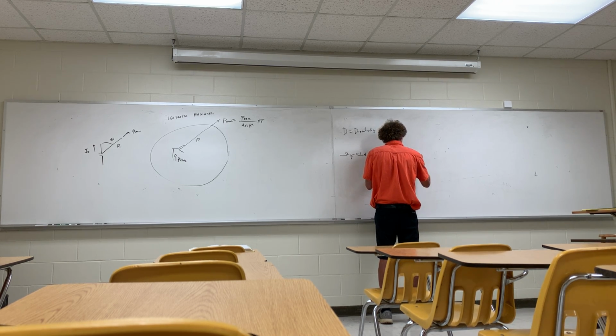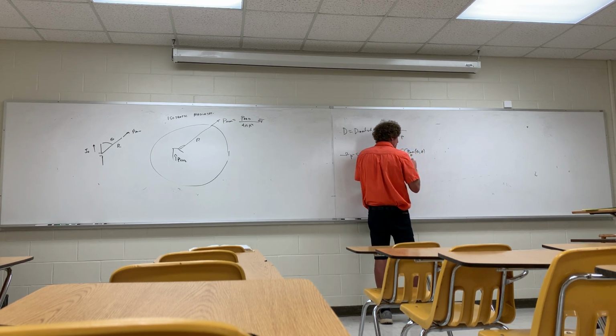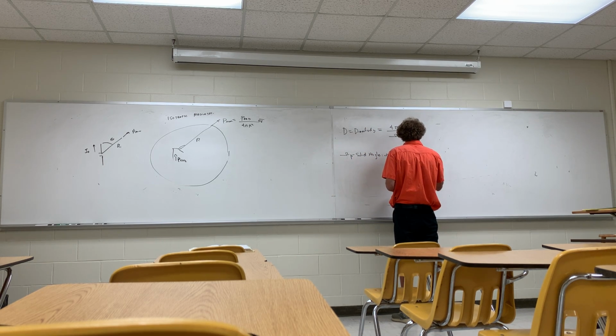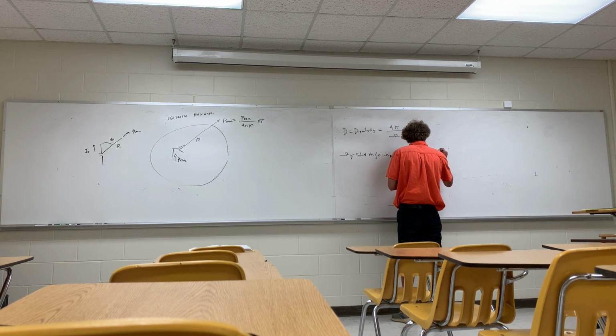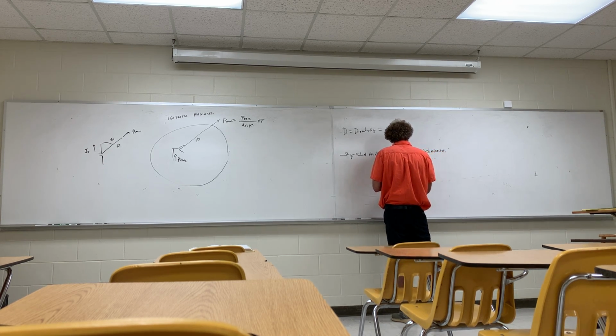So it's Pav, and it's normalized. I think he just calls it Pn in this book, but it's the average power density, but it's normalized. And that's a function of theta and phi. And it will not be a function of R. It's that integrated over the surface, and the surface of a sphere of radius 1, which the differential surface area would be sine theta d theta d phi. Theta would go from 0 to pi, and phi is 0 to 2 pi.